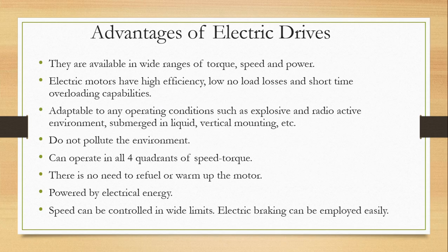And we can just see what the main advantages of the electric drives are. You can see over here, the electric drives are available in a wide range of torque, speed and power. And electric drives have high efficiency. The no load losses are low. You can overload them for a short time, that's okay. And it is able to operate in most conditions, that is explosive or radioactive, because you are providing electrical energy, and it's not going to create any spark, and it's not going to create any explosion. You can submerge it in liquids. You can provide it in areas where vertical mounting is required. So all of these are not difficult if you are using electric drives.